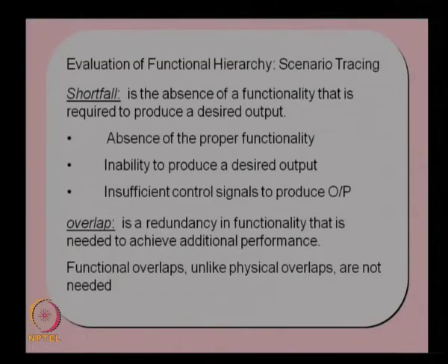So like this we will keep on dividing these functions till we reach the stage where we do not really need to decompose them, because some of these functions will reach the lowest level of function where we can really identify a component which can actually provide that function. So till then we will keep on decomposing each function into sub functions, and we will be getting many diagrams like the A0 diagram, A1 diagram, A2 diagram, or level 0, level 1, level 2 diagrams.